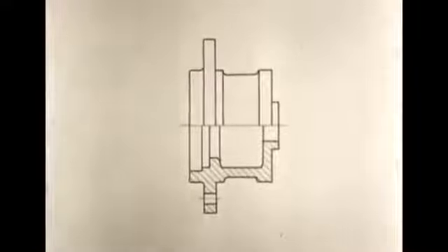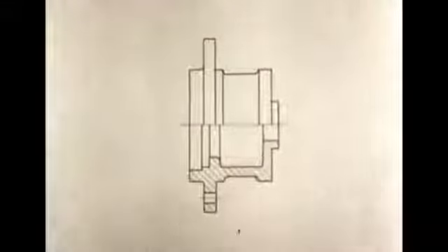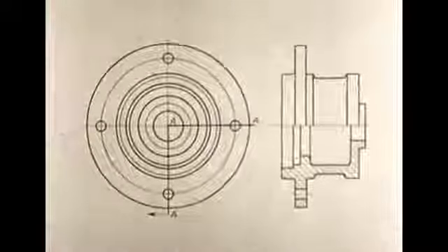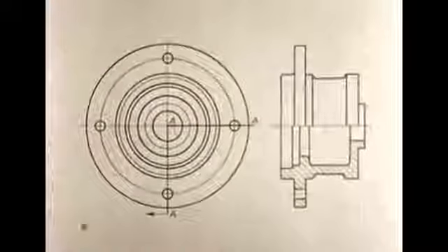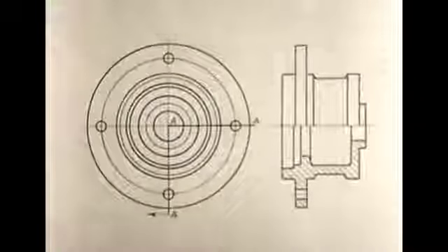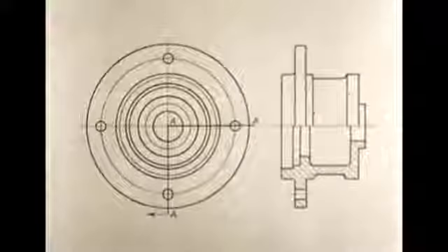When you draw a half section, use a center line through the view, but not an edge line. No edge should be shown because the cut is imaginary and the object is actually uncut. Show the cutting plane line, arrows, and reference letters. Use a half section whenever it will show the details of the object more clearly than a full view or a full section will do.